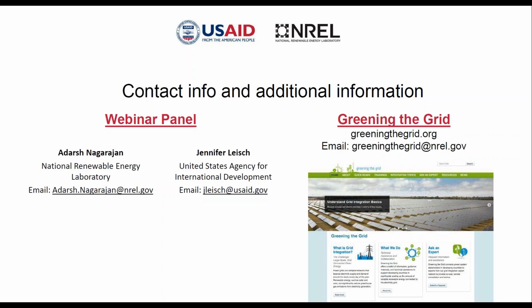And as I said, if the device is still operating and there is a fault, it could be a fire. In order to avoid that, what NEC did is come up with a red button. If there's a solar panel on the house, and the person doesn't know whether the panel is operating or not, what the fireman should do is go and press a red button, a single switch outside the house that disconnects the device, irrespective of whether it's ride-through, not ride-through, frequency event, voltage, and whatever it is. Personal safety takes the priority there.